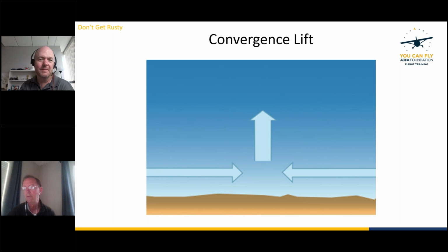So thermals can be a little bit turbulent, but not too bad because you're flying at relatively low speeds. Ridge lift can be reasonably turbulent because of the proximity to the terrain. You get a lot of variation in the airflow, and so you can get a certain amount of turbulence. In fact, it can be pretty bad. The higher you get above the ridge, the more that would settle down. And the wave is absolutely smooth. The way that you know that you're into the wave is everything all of a sudden is just silky smooth.